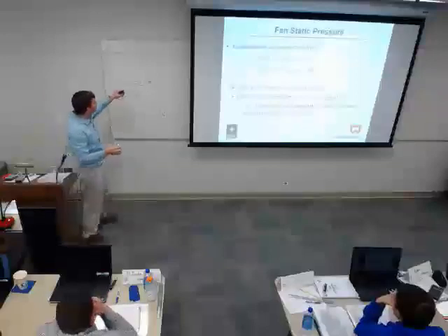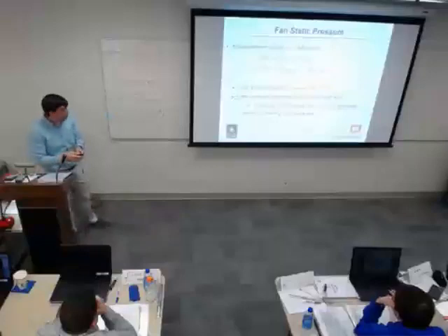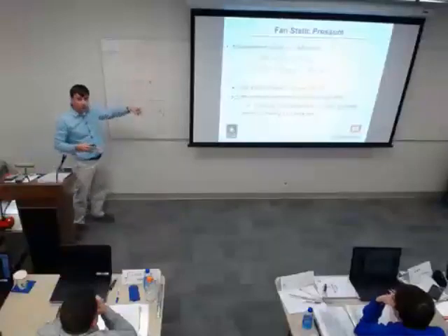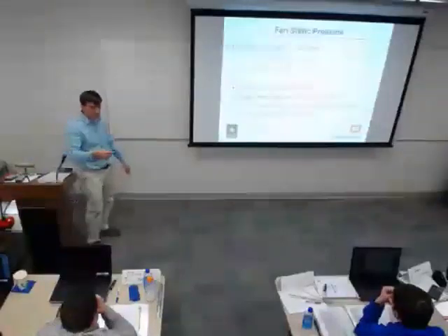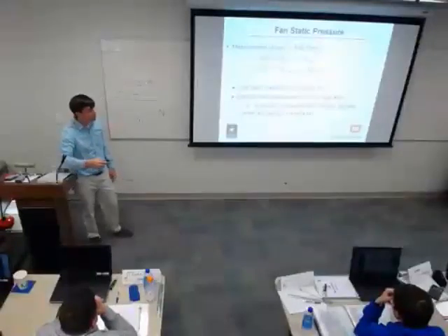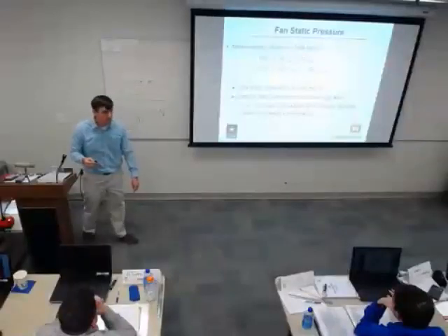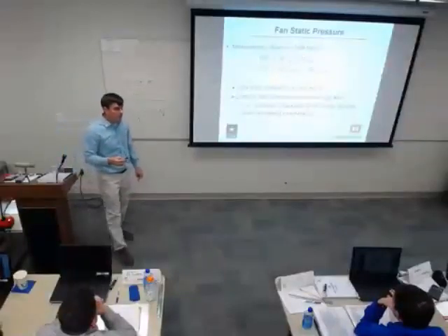Okay, so if you have an air handler scheduled on a piece of equipment, that's actually both numbers, but the total static pressure can be different for various vendors. So you're always going to see external static pressure. You might also see a total static pressure on your equipment schedules. We good with that? That number, does the TAB need to verify it, or is it just going to be?